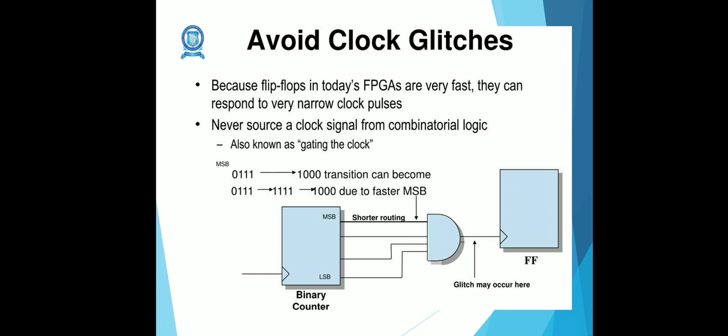As we see, clock skew will increase the minimum clock period and reduce the maximum clock frequency, because clock skew effectively adds to the sequencing overhead, reducing the time available for useful work.